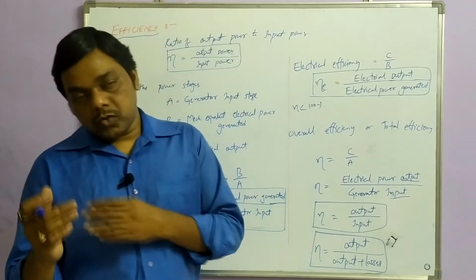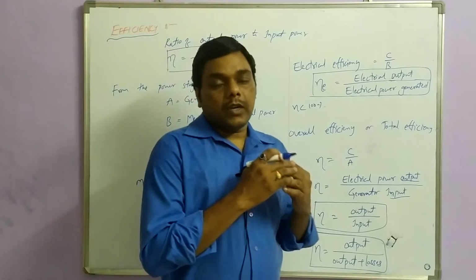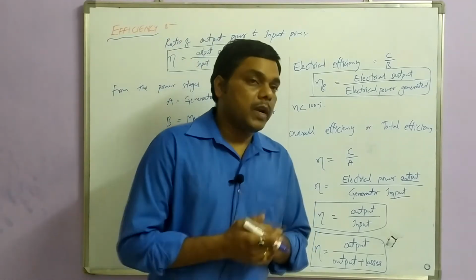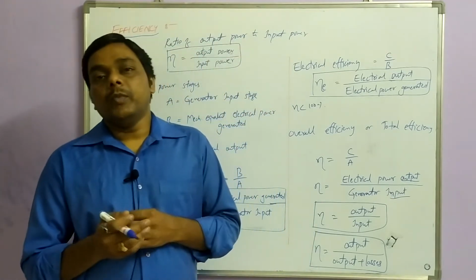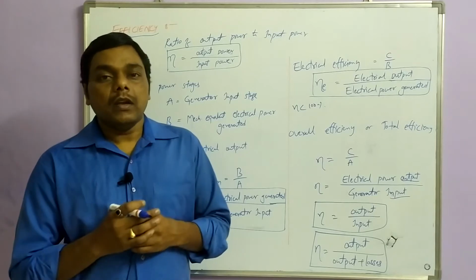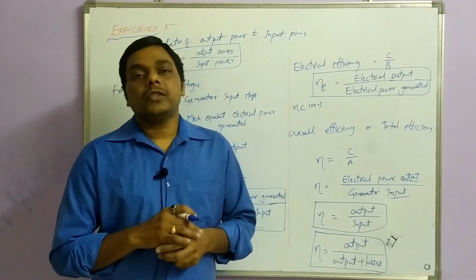Making laminations will reduce the eddy current losses, and with proper maintenance, proper lubrication and greasing, we reduce the mechanical losses. This is about electrical efficiency.